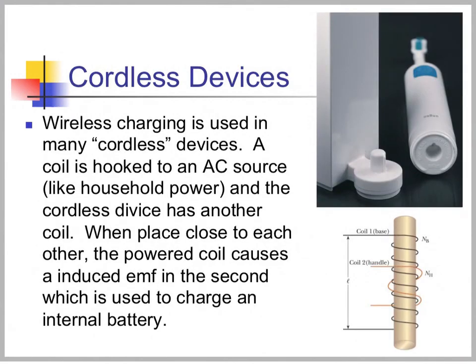So let's say I have two solenoids, A and B. They're spaced close to each other. They share the same cylindrical axis. And they have 400 and 700 turns respectively. A current of 3.5 amps in coil A produces an average flux of 300 microwebers through each turn of A, and a flux of 90 microwebers through each turn of B. Calculate the mutual inductance of the two solenoids.